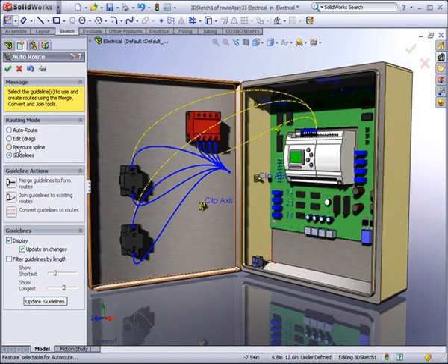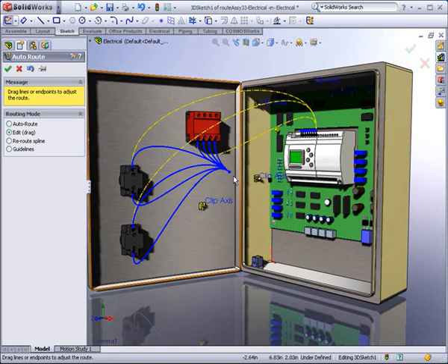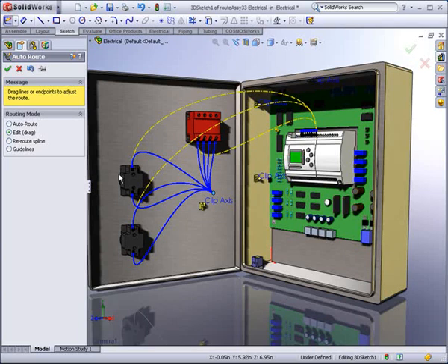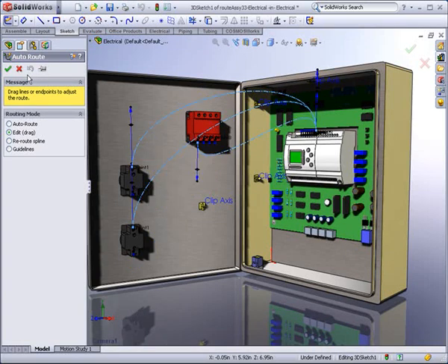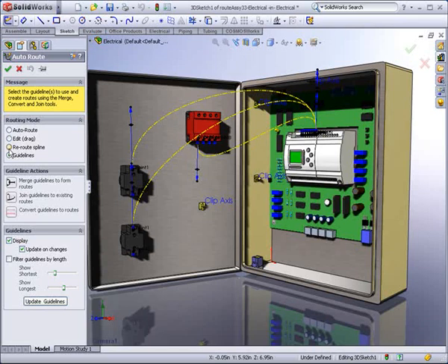If the wire route is already known and the clips and components are already placed, the Auto Route enables you to automate the routing of the wires by simply selecting the guidelines and the clips through which the wires will pass. In this way, SolidWorks lets you automatically route the wires, but still provides flexibility, so you can decide how you want to group the wires in a harness.